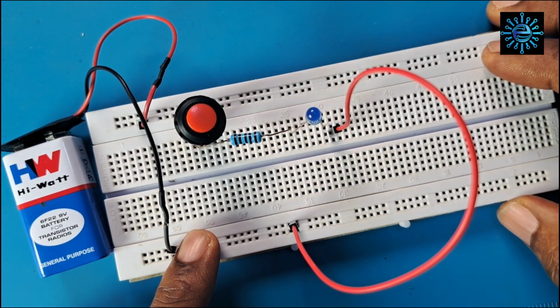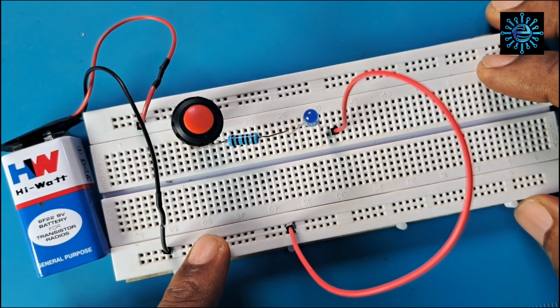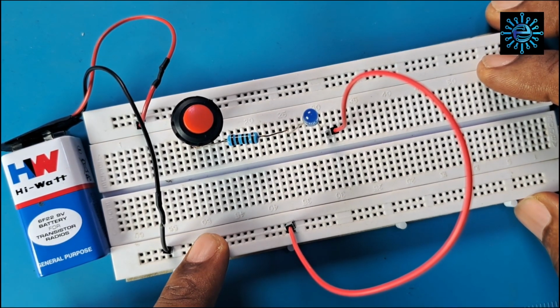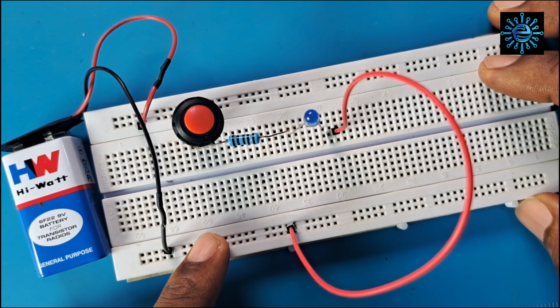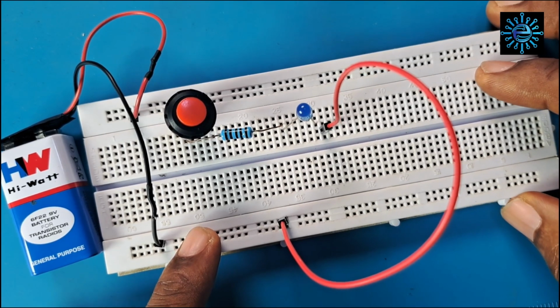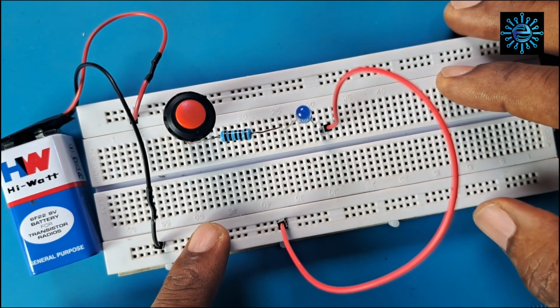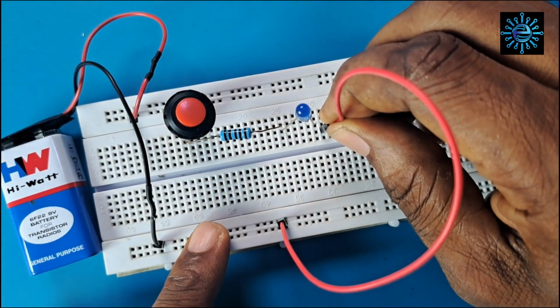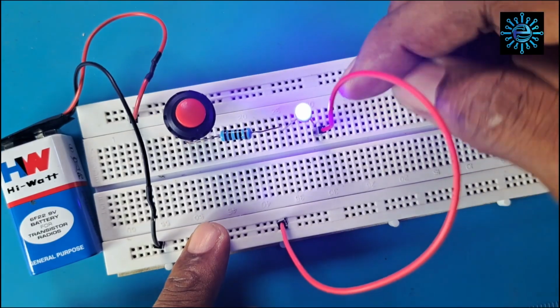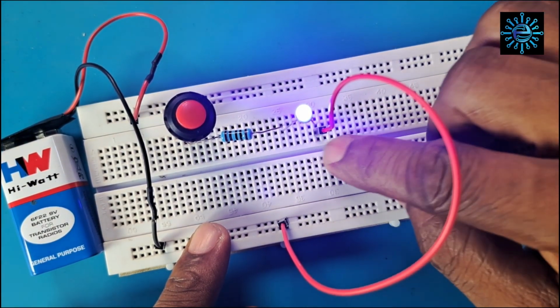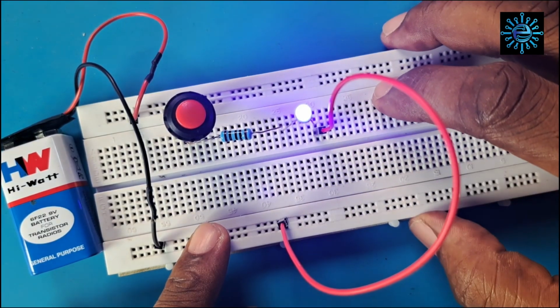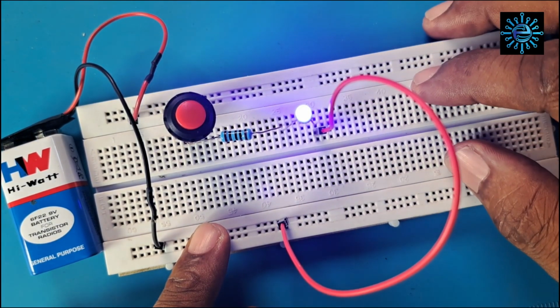So when you make your circuit and you discover that it is not working as expected, you will go ahead and troubleshoot it. And one of the things you can do is to check if the component legs are inserted in the correct holes. So to fix this kind of problem, what I would do is to move this jumper wire here and put it here, and you can see that because the switch was turned on, the moment I plugged the jumper wire into the appropriate hole of the breadboard, the LED came on.